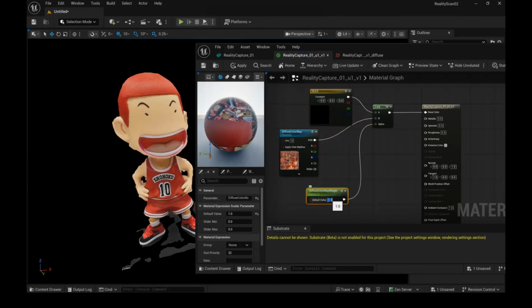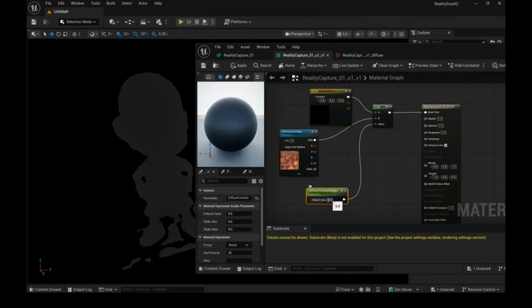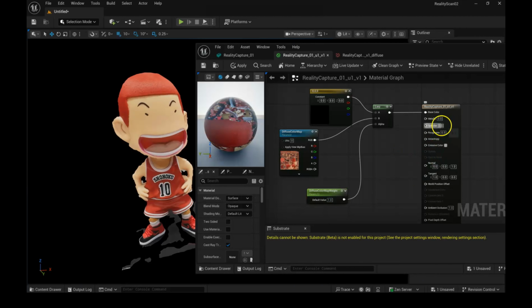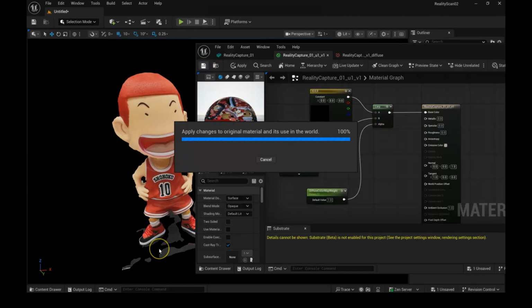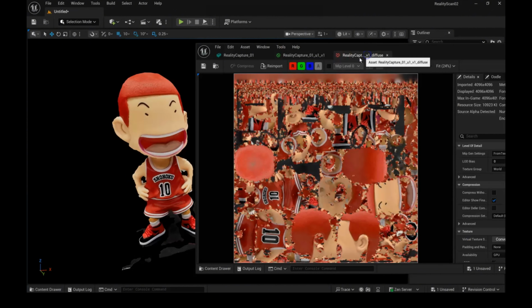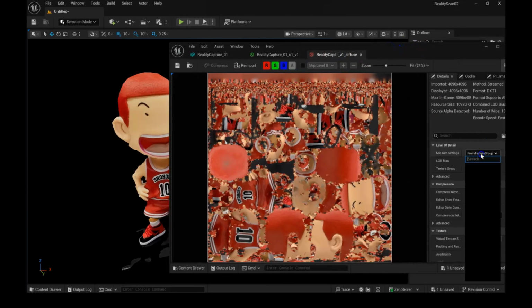In the material, we can adjust the options here, and we can adjust the diffuse power. The diffuse value is 1, or we can make it more vibrant by having a power greater than 1. Okay, I'm going to keep it at 1. On the right side, I'm going to push the specular to 0, and pull down the roughness to 0 as well. I want these not to affect the natural look of the material, and you see it's more realistic compared to before. Of course, this is about lighting at the moment.